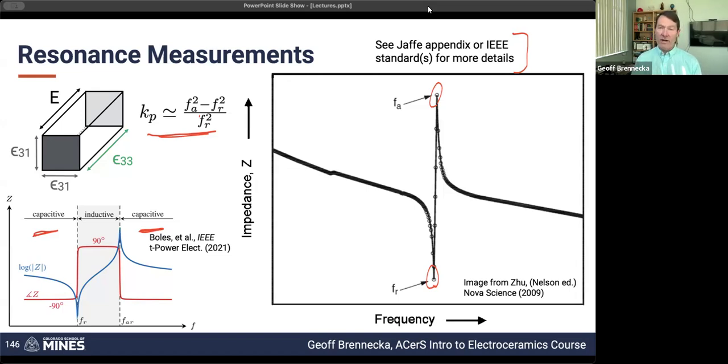One other thing that I wanted to point out on this slide, you'll notice there's another blip right here at lower frequencies. If we kept going higher, you'd see others showing up. So you can get multiple different harmonics from these. If you remember, the whole reason that we see this electrical resonance is because there's actually a mechanical resonance in the sample. Just like a tuning fork, there's a natural resonant frequency based on the geometry of the sample.